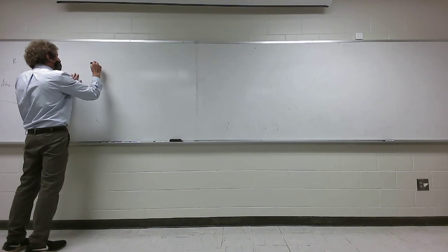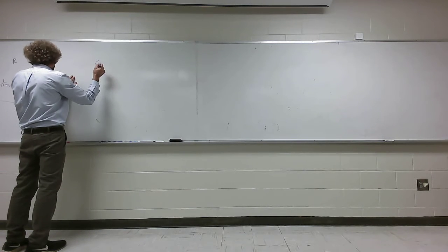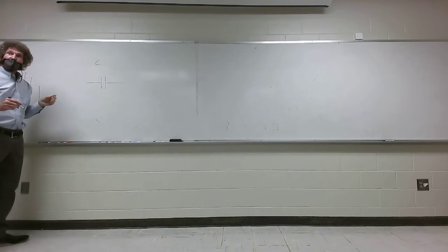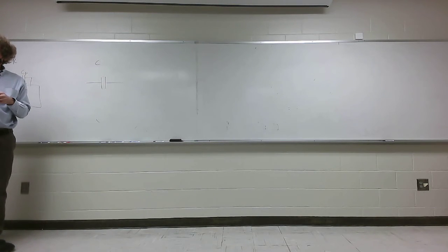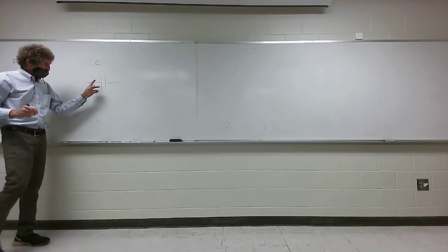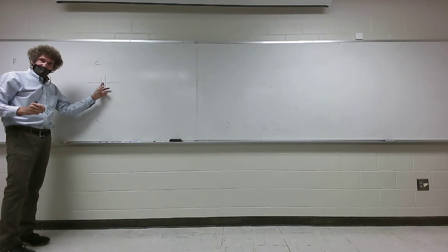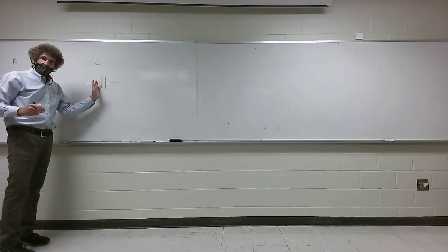If we take a look at the model for a capacitor, and this is the high frequency model, you start with the element. This particular model is not appropriate for an electrolytic capacitor because they have a lot of leakage, so you would see a leakage resistor right inside of here. Like literally it would be a parallel one.